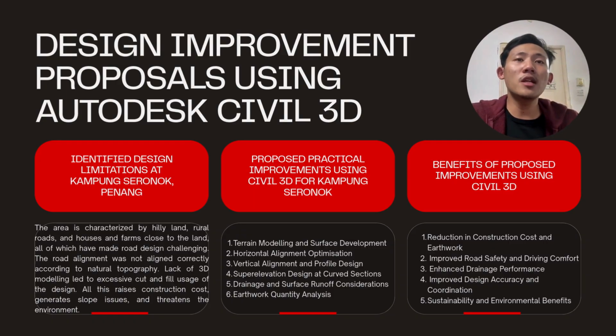Today I will briefly present my project on design improvement using Autodesk Civil 3D for a road at Kampung Seronok, Pinang. This project focuses on a rural and hilly area where road design is more challenging due to uneven terrain, nearby houses and agriculture land. The initial road design had several weaknesses because it was not properly aligned with the natural topography. As a result, there were issues such as excessive cut and fill, steep slope, limited sight distance, and poor drainage, which could increase construction costs and safety risks.